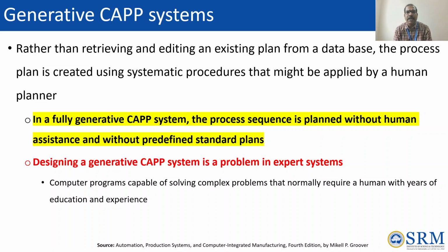With that, we give a unique identification number to the product once we receive an order. Then we check that number against the database, because we have done similar work in the past, stored it for that component, prepared the process plan and executed the manufacturing. So the overall process plan for individual components is stored. Once we receive a new component and give it a code, we match it with our database. If the same plan is there, fine, we can directly use it.